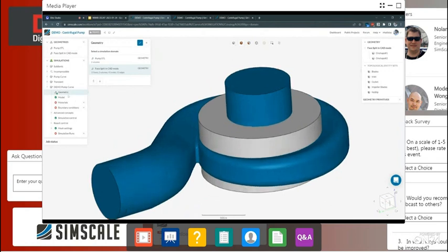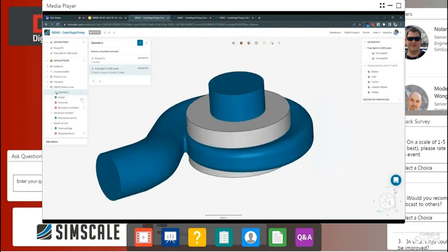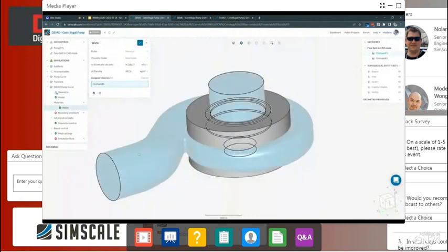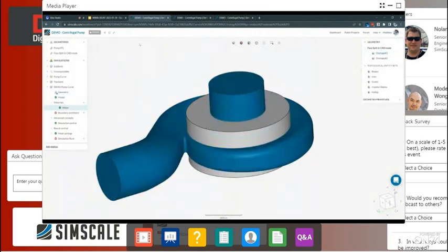And we see here that the geometry is automatically added in to this simulation that lives in the tree over here. Now I'm going to work top to bottom, and generally we see where SimScale has validation checks, so it has certain information that it needs. If that simulation is properly set up, you should not see any red circles in the tree. So it's a guided workflow. First off is defining our material. Fairly straightforward. We're going to just flow water.